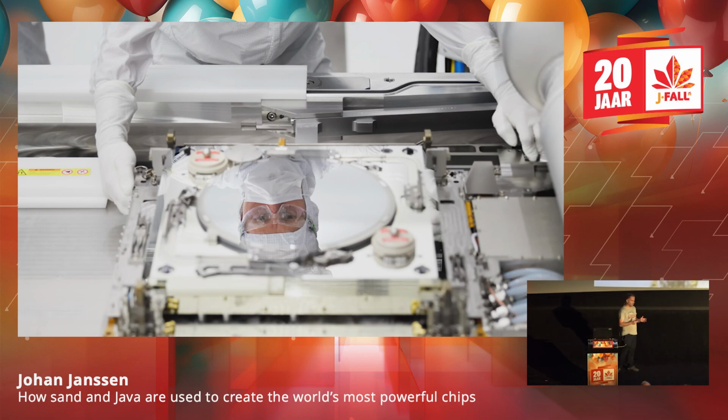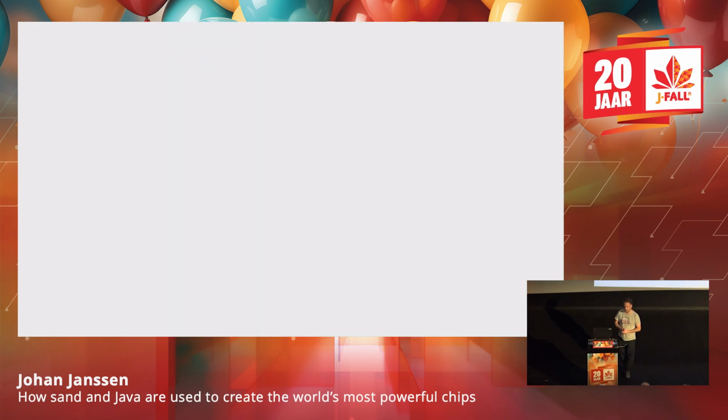Then that wafer is placed on a magnetically levitating wafer table. It's a mouthful. Basically it means we use magnetic forces to keep the wafer floating, because if we clamp it, it will bend a little bit, and that bend will result in less functioning chips. So it needs to be really accurate. This wafer has the resist, the chemicals, on top of it, and then we need to print basically with light on those chemicals. So I'll show you how that works.